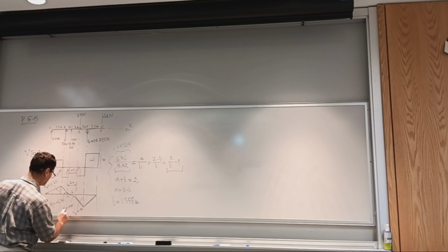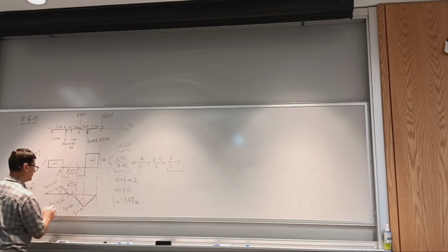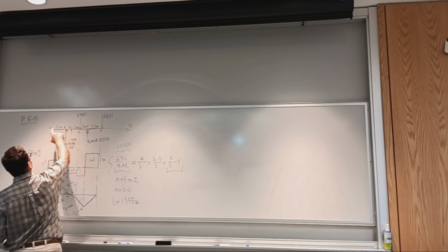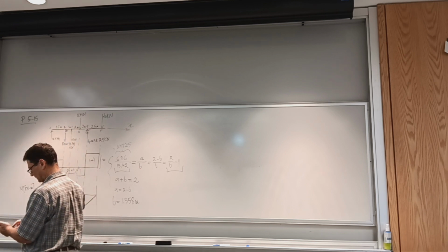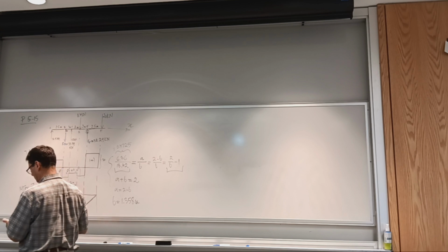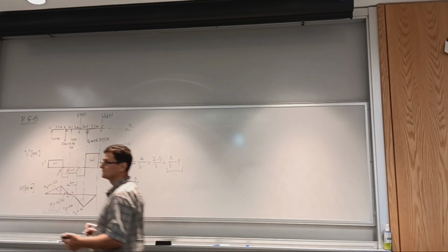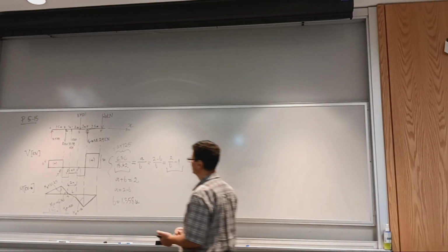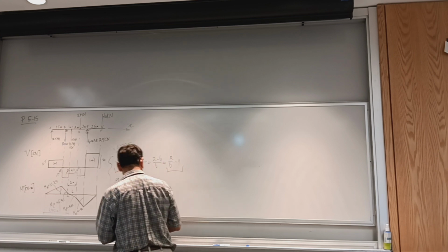So if you were to position this from the left end, this is going to be equal to the value that we calculated, subtracted from 5.5. So I said 5.5 minus 1.358 equals 4.142 meters. Was it clear what I did? So I use similar triangles. If you like instead to work with the equation of the moment, well, we can do that too.